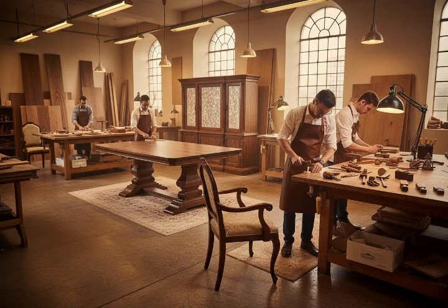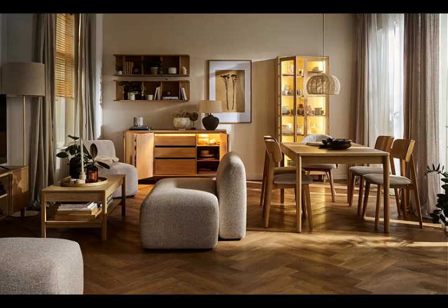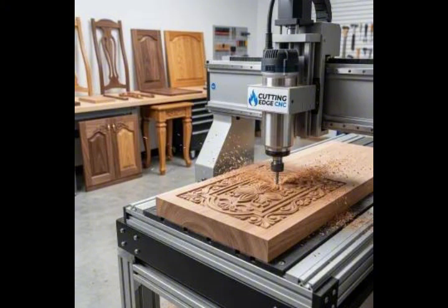Final thoughts. Perfect CNC machining isn't achieved through luck. It's the result of understanding how spindle speed, feed rate, chip load, cutting depth, and tool geometry work together. Every workshop, every machine, every cutter, and every material behaves a little differently. The goal isn't to memorize one perfect number. The goal is to understand the relationships between the parameters so you can make intelligent adjustments whenever conditions change.